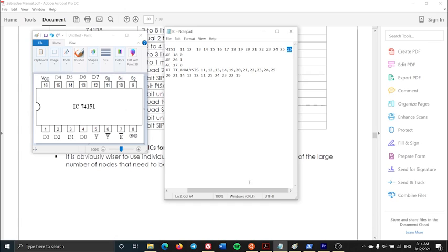And this is the plus VCC that has to be set to 1. This is where it is set to 1, plus VCC. This is where the ground is set to 0, and this is where the opposite of enable is set to 0, such that the enable will be 1. And the truth table analysis will be performed on the select lines and the inputs.